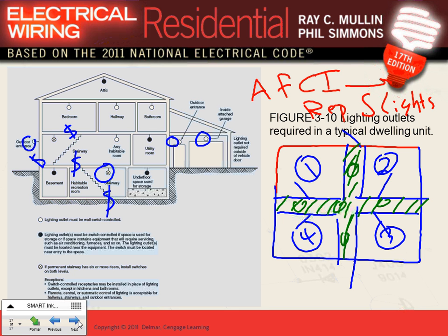Okay. Don't forget that in dwellings, guys, all receptacles must be tamper proof, right? You've seen the tamper proof where you have to push both slots in order to get into the energy there. All receptacles in a dwelling or apartment must be tamper proof, 15 and 20 amp, 120. If you have 40 amp, 50 amp, no. And if they're outside, they also have to be, anybody remember what? Weatherproof. That doesn't mean anything right now, except when we start doing takeoff. When we do takeoff on this apartment, you're going to have a weatherproof, GFCI, tamper-proof receptacle. It runs you $21.